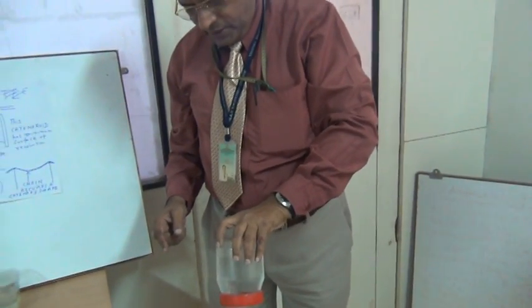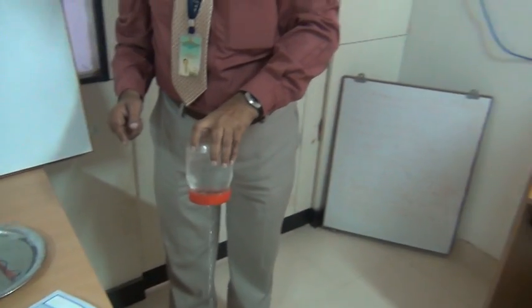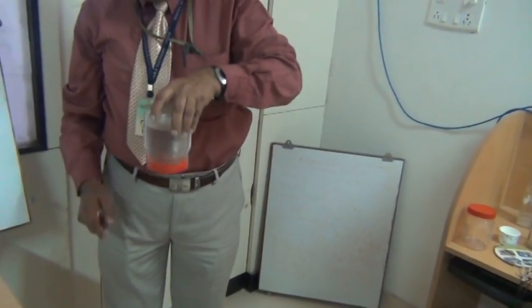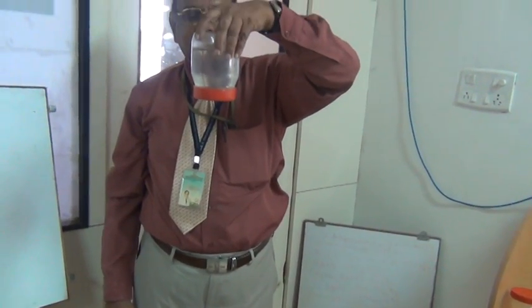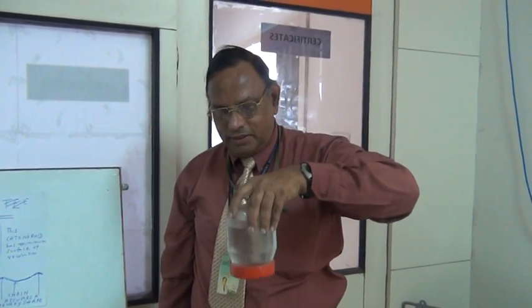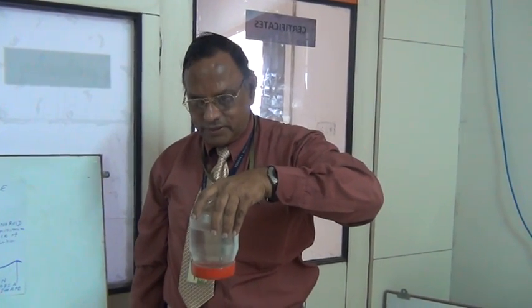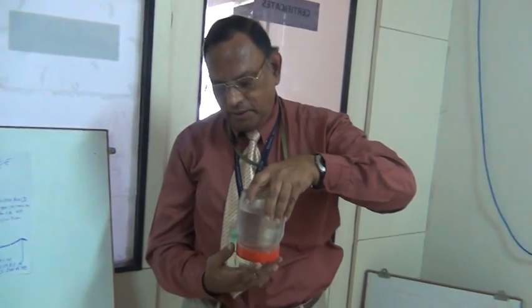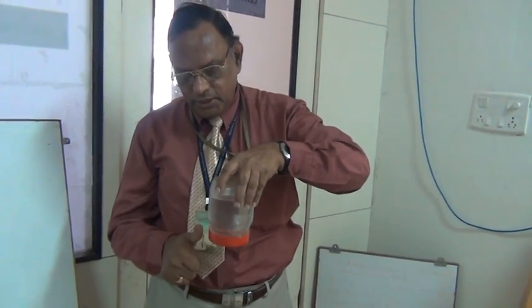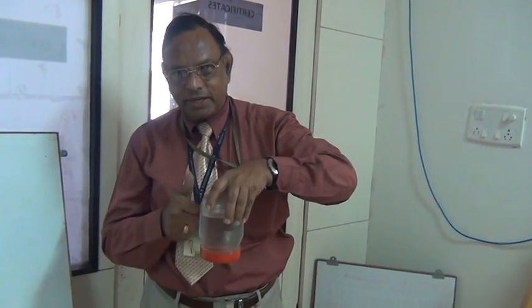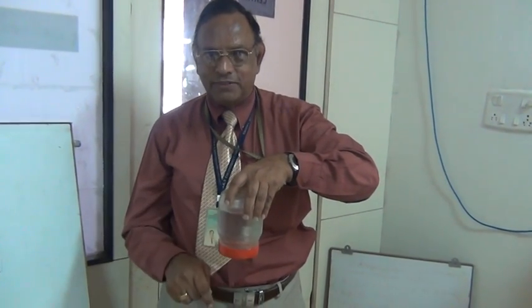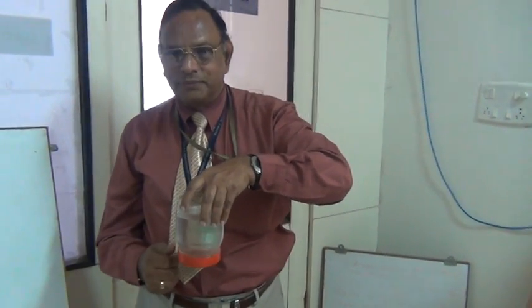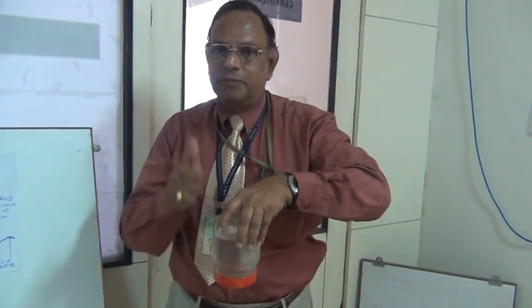But if I tilt it a little bit this way or that way, water may fall from the sides. But when I put it again vertically, water doesn't fall, because water has to come only through the mesh, and because of the surface tension, the water does not flow downwards. So it is defying gravity. Actually, water is defying gravity. So due to the surface tension, there is an equal and opposite force in the upward direction defying gravity. G is downwards. The force due to surface tension on this column of water is upwards.